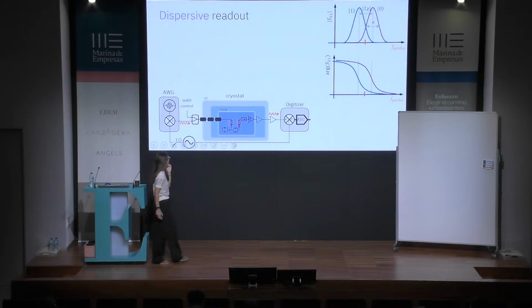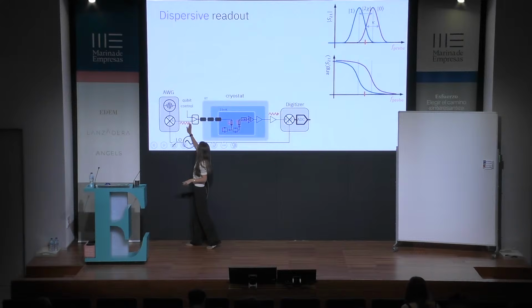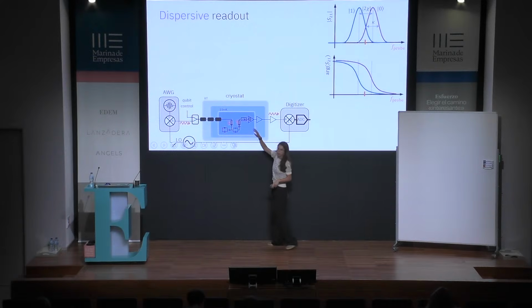And the way in which this is done in practice experimentally is that you would put your transmon and resonator inside a cryostat with a line arriving to them and another one that you will use for readout. And you can generate some signal at a certain oscillating frequency, up-convert it, send it through your attenuated lines in the fridge. Then maybe in the output you have a bunch of amplifiers, some quantum-limited amplifiers at low temperature, some isolators. And then you end up getting your signal, down-converting it again to lower frequency, and see what you get.